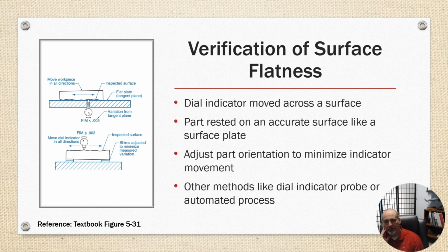I haven't seen a whole lot of shops that are going to have a granite surface plate with a hole drilled in it, and then they're going to want you to slide a part across it. If you're concerned about flatness, just that excess of movement across the surface plate is going to warp and wear down the surface plate eventually. So typically you support it by 3 points.